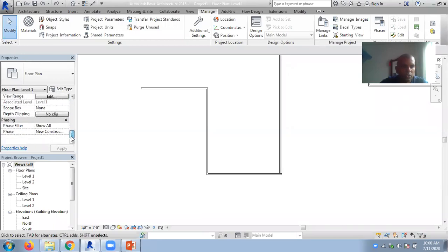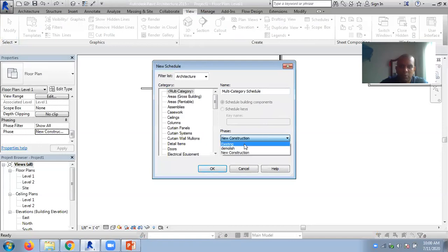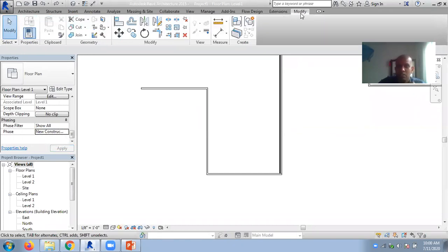I will go through this later. Say there's some error popping up now. But remember, we can delete these things. Sorry, we can create different phases and go to the QS table. And now this demolished phase is coming. So you can get the material cost and other quantities from the demolished phase, or as all building values or the new construction values. So that is the usage of these phase tools. So phase tools can be incorporated with the demolish tool also.